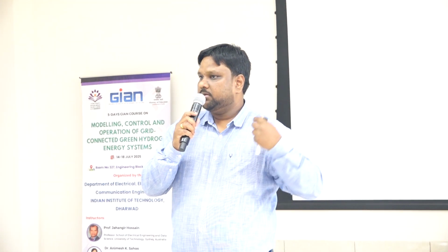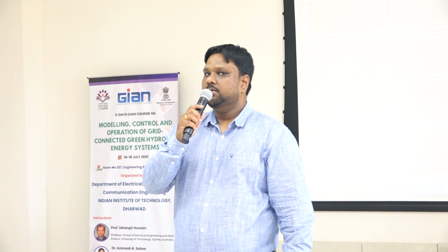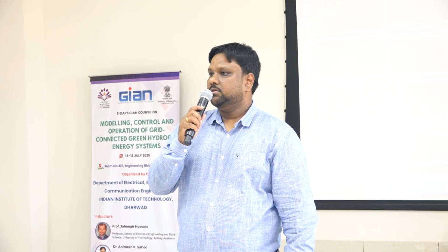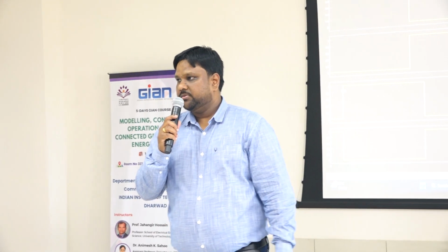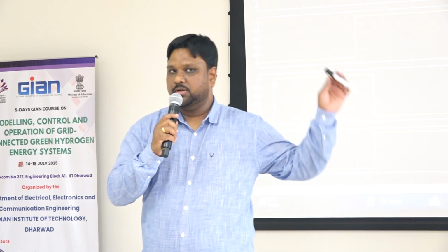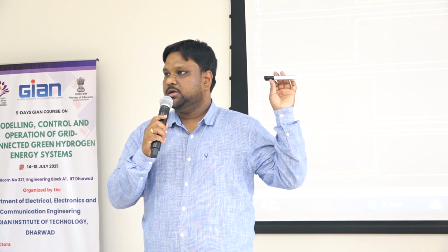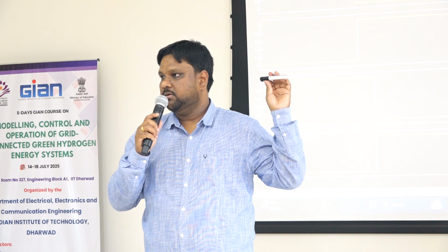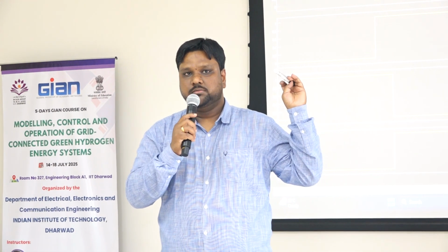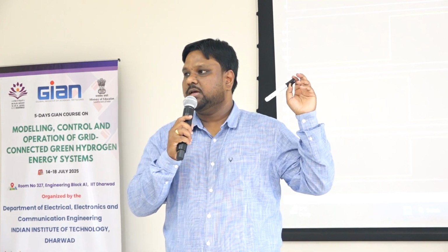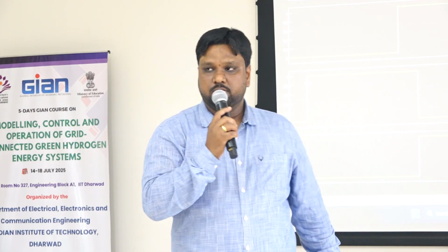So now we'll do that shift through a closed loop control, where we are showing you one type of sliding mode control. Yesterday I told you several types of sliding mode control, right? Also today we showed you the theory. For that we require some feedback signal measurement, okay? In this case we are trying to control the output voltage, the voltage across the capacitor.